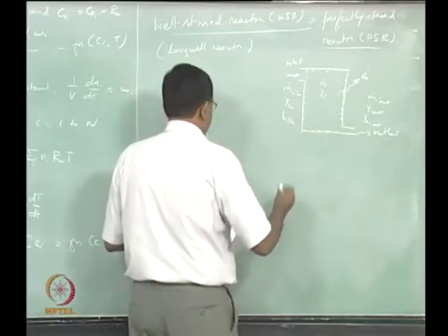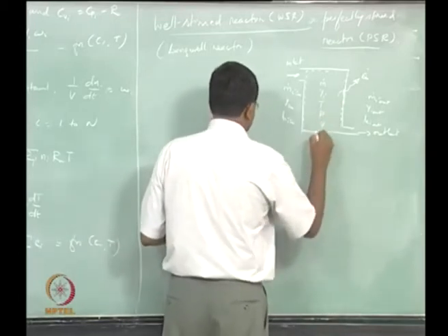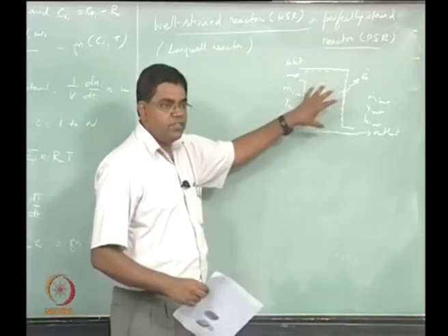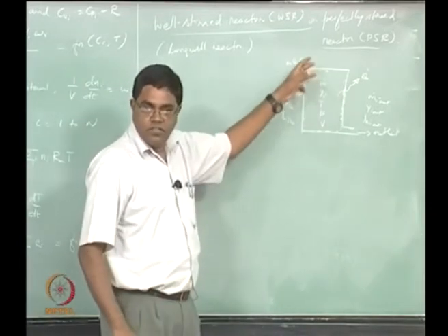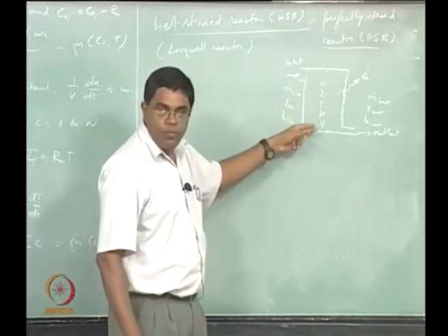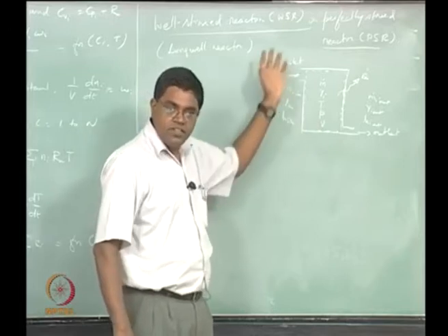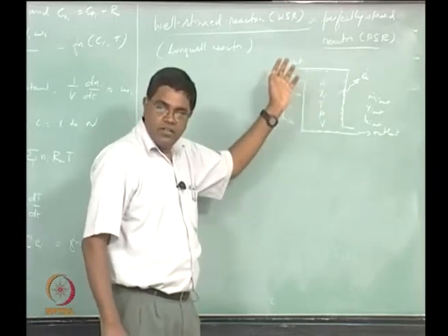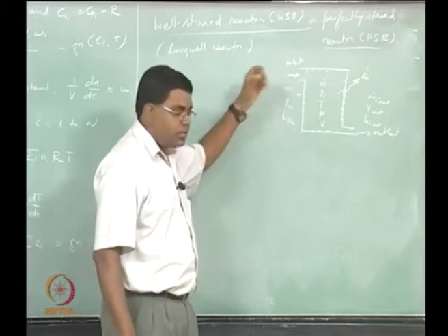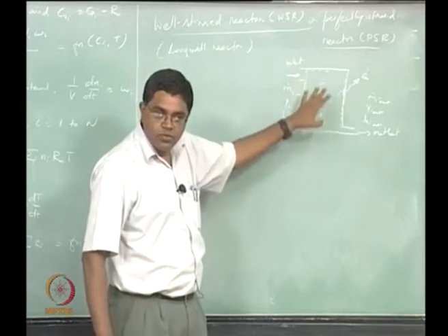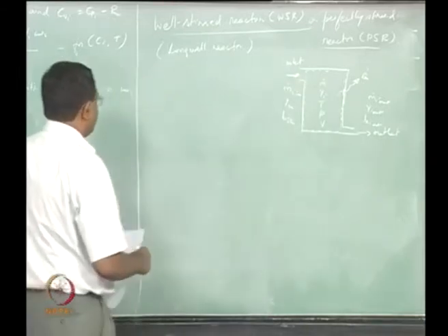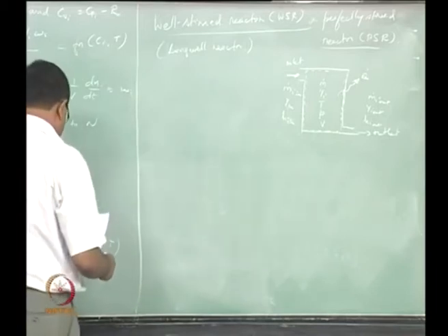So then of course it has a certain temperature, pressure and volume, and ultimately we will see this, there is a relationship between these. It is like you are handling a certain m dot at a certain pressure and volume, that will relate to a certain density, and with that density for these mass fractions you will now get the partial densities of each of those species to be fixed correspondingly and so on. So there are relationships that we will be working out among these.